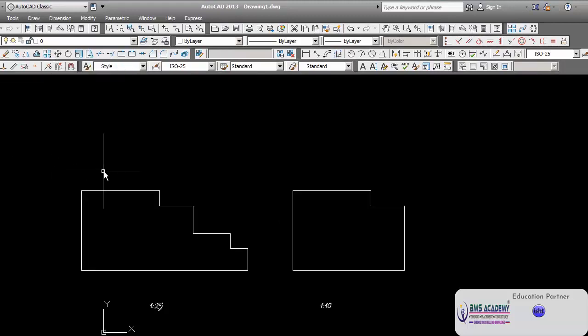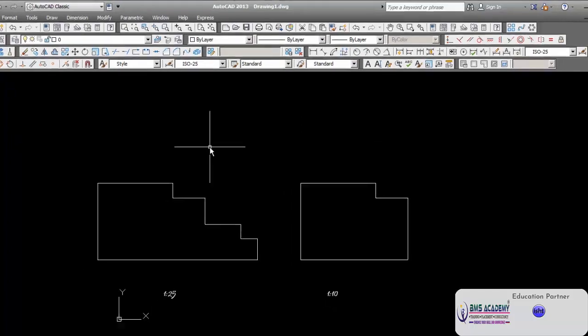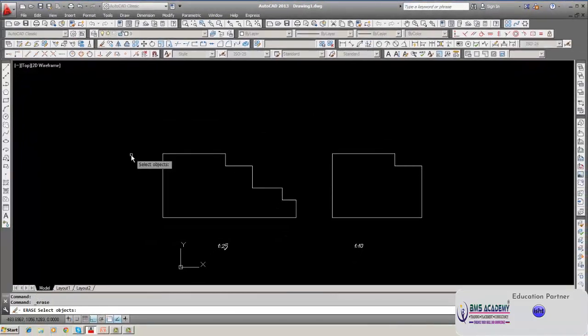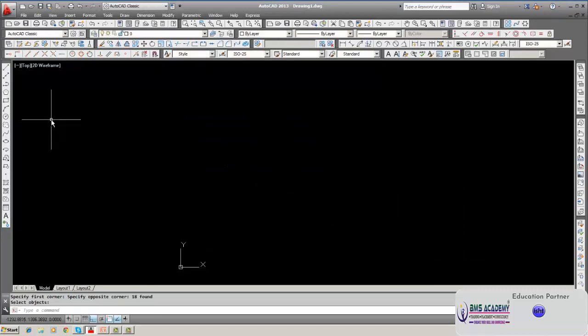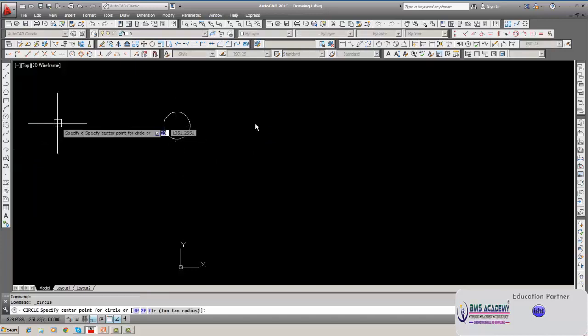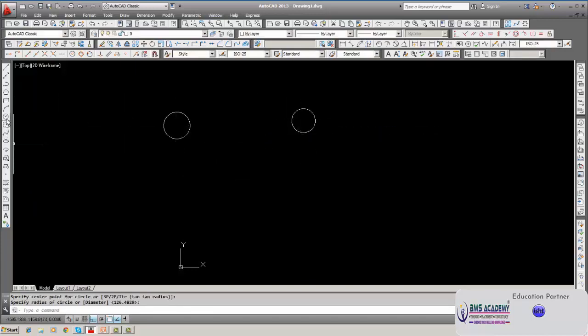Now I have shown you how to dimension the circle and other things also. So now I will erase this. Leader dimensioning also I will explain. Sometimes in drawings you may have to dimension the leader, circles particularly. Suppose a threaded hole, let us say. Sometimes the diameters will be dimensioned with a leader. Instead of diameter, you may want to have some description, let us say.